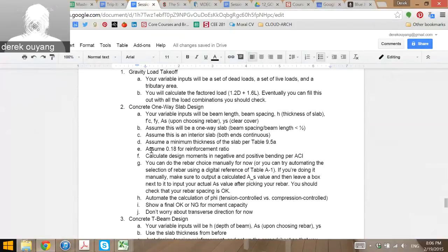Each one-way slab is really dealing with this condition here. Like you're designing a 1 foot by, this is 1 foot by, that was L. It could also be LN, right? It's a clear span effective length. But the L is the big question you have here design-wise. You take that L, you're then designing a slab, which is 1 foot long, and then you're putting a certain amount of rebar per foot, right?